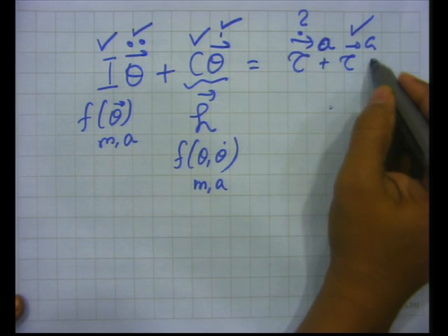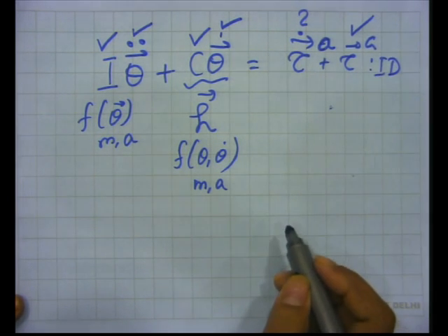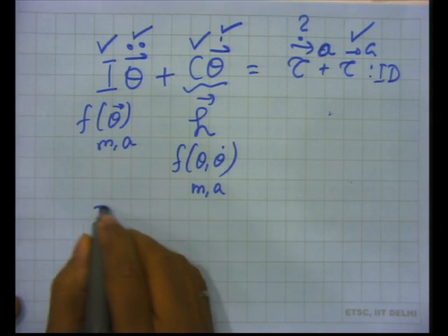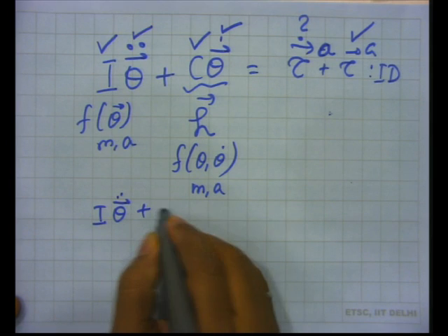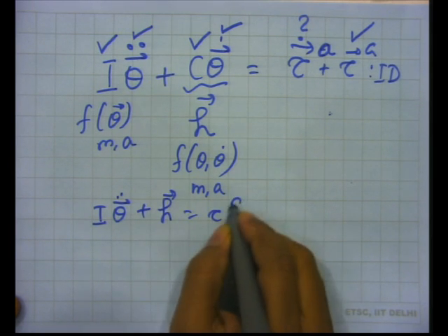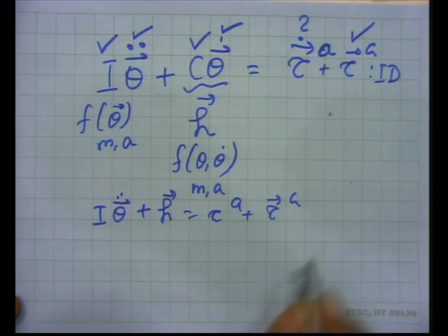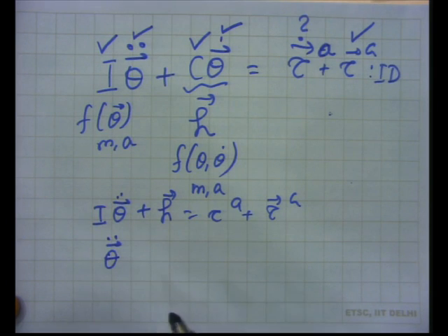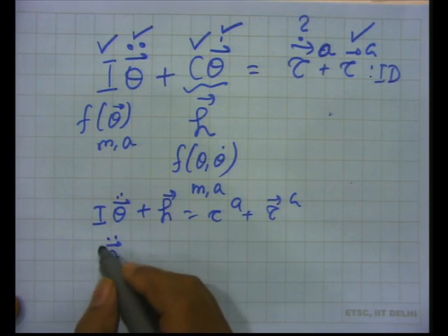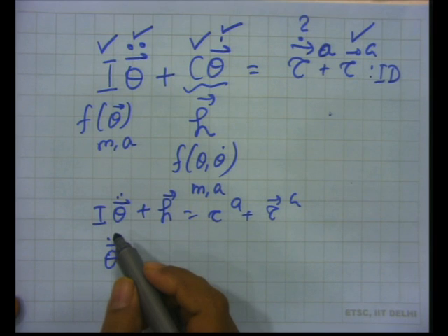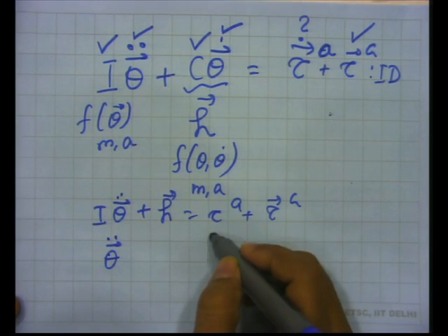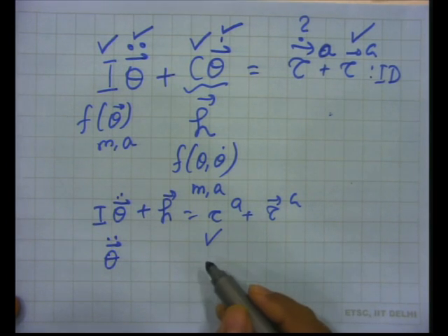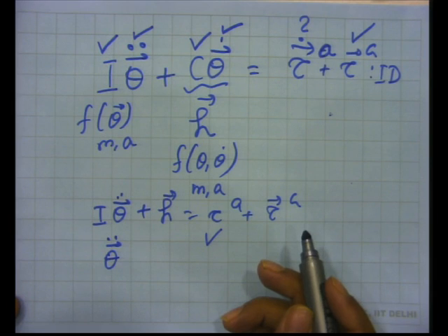So, this is my inverse dynamics. In forward dynamics, my problem is just the opposite. So, I have this equation of motion, tau A plus tau G. Now, here I would calculate theta double dot first. What are the things known here? System is given, so mass, inertia they are known, but theta I do not know where it will go. But what I am providing is what will be my joint torque, and then I want to calculate what would be my theta, theta dot, theta double dot.